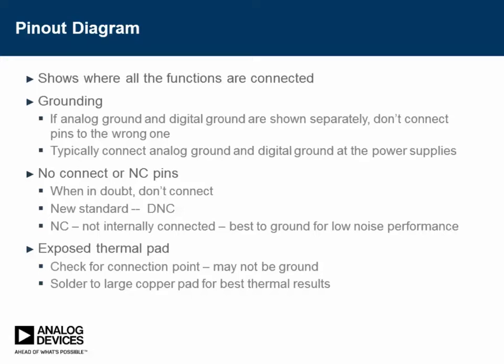In most cases, for the NC pins, if they're not specifically called DNC, then it's good to just ground them, and that will keep any sort of pickup noise from getting into the package.